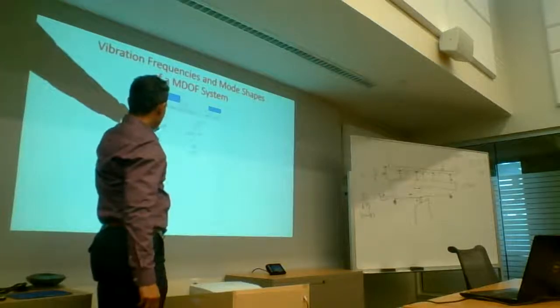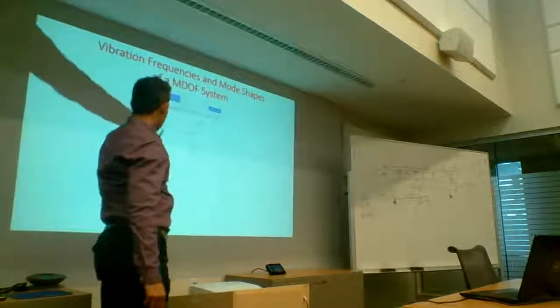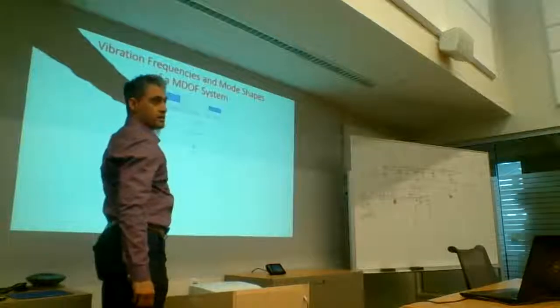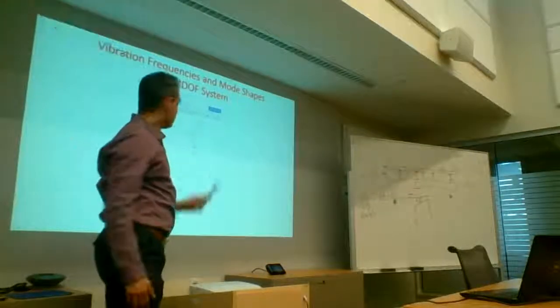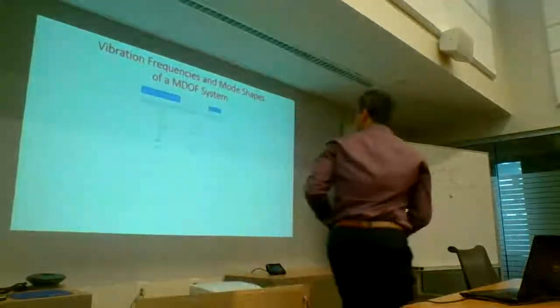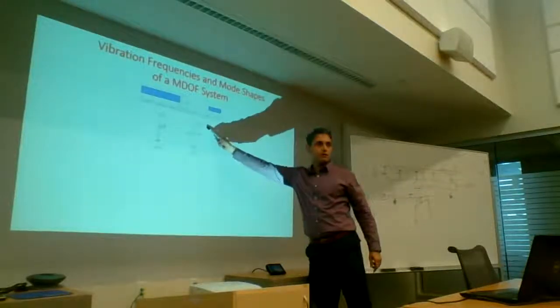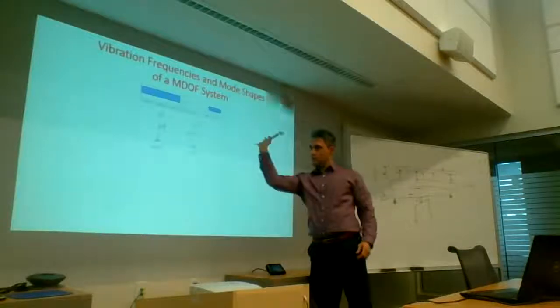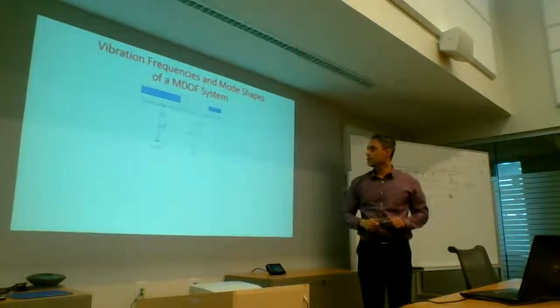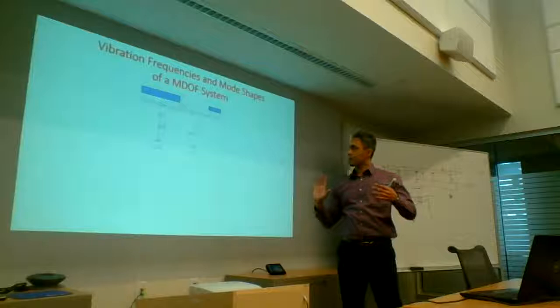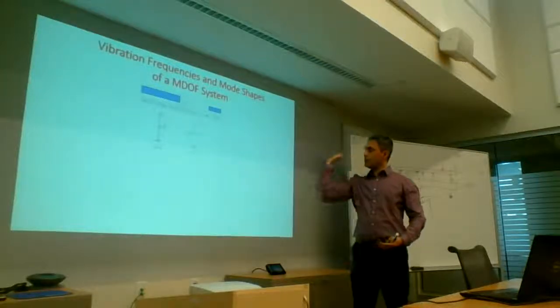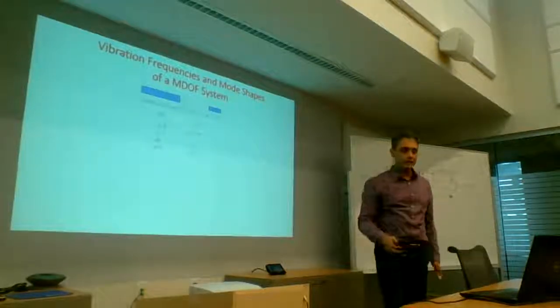So this is 0.62, this is 1. That's the ratio. You can have this as 620, and this as 1,000. Same thing. This one here is minus 1.618 and 1. So this is now going in some reversed manner. The first floor is being pushed this way, the top one is being pushed the other way.